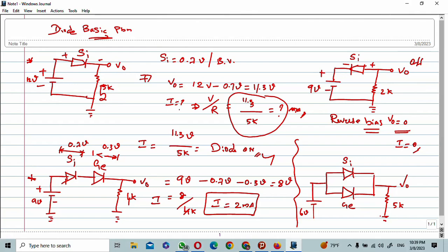So in this session, finally we are going to conclude the basic concepts we apply in diode circuits. Okay, so now you can check. There are two diodes. Here the 6 volt will travel around the germanium, and around the silicon and the germanium. We will get different output voltages. So for the silicon, here we are going to get 5.7 voltage.